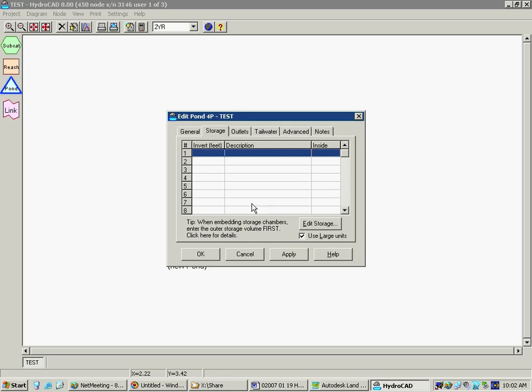There's a lot of things you can do with that pond set to a catch basin. There's also an infiltration factor available. You can set that in there as well. Okay. All right. I guess we've been spoiled here with HydroFlow, so we haven't had to use it for conveyance purposes. I agree that HydroFlow is going to be easier to use on conveyance. I can see that. But with the new BMPs that he's pushing here and calling for infiltration of the 2-year volume and all, I think this program is going to be very valuable in trying to apply some of those principles. I agree.